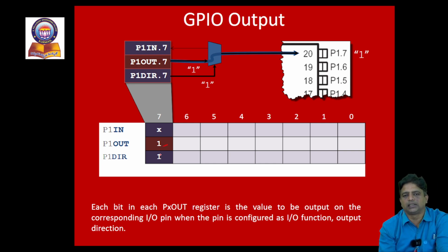Now, based on the strategy we are using, if 0 is off and 1 is on, we will release the values 1 for on and 0 for off. If it is used in active low condition, sometimes 0 is on and 1 is off. Based on the application, we will release either the on or off situation. So this is the way of handling. Somewhere if we use a port pin to behave like an input pin, then we will make use of one of the registers called REN, receive enable pin. In the coming arrangement, we can see that arrangement.